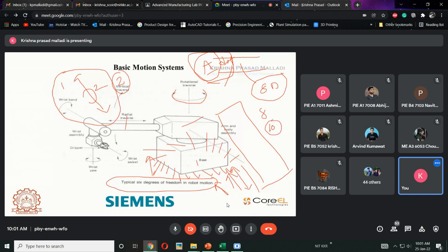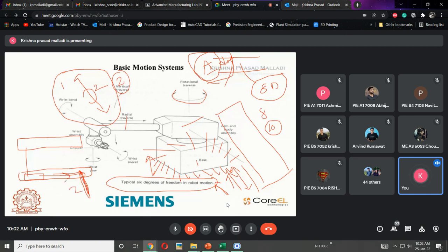in spray painting applications, where the automobile body comes into a place and it will be fixed at a location. The robot is not only fixed in this location, it will be given some rail here so that it will do the operation at the same time. Simultaneously it will move and do the operation. If it is defined in the upward and downward direction also, then it will be called something else. So based upon the movement of the robot, this additional axis will also be considered.